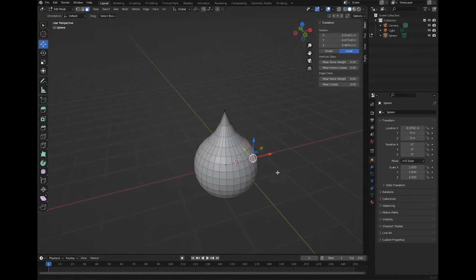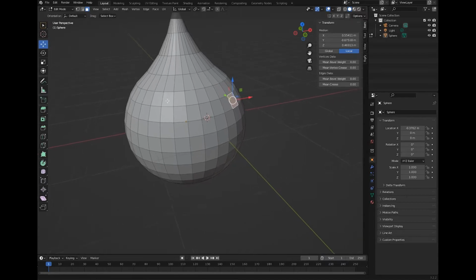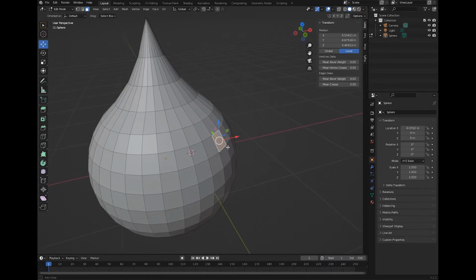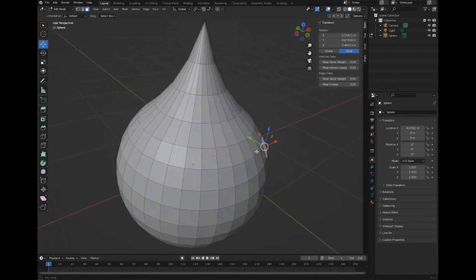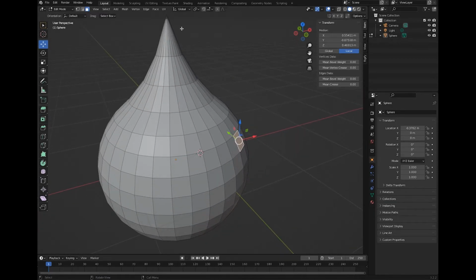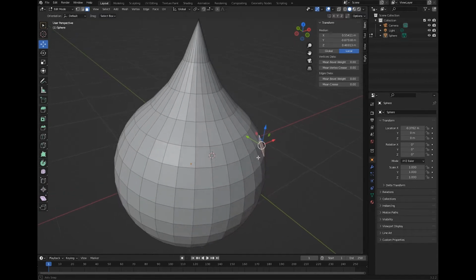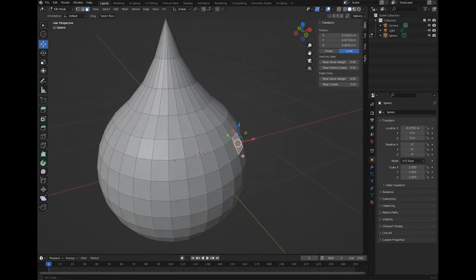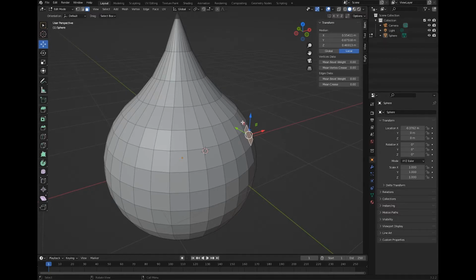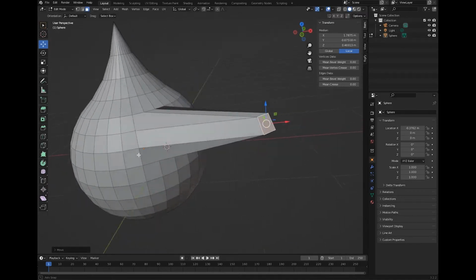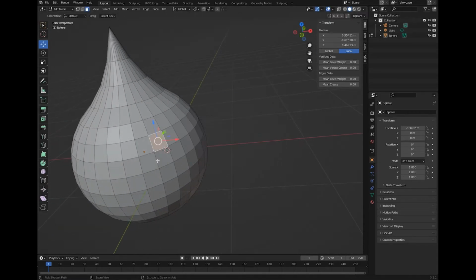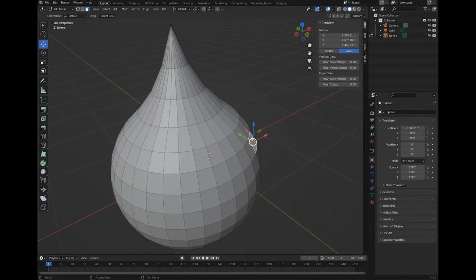The one thing I want to show, remember the way you move, the same way we did in object mode, is what direction you're moving based on the axis. If it's a global position, I'm not actually using the normal of this face, I'm just using the object position. So it's not really what I want, for it to move that way. I want to move along the normal, the direction this face is pointing.